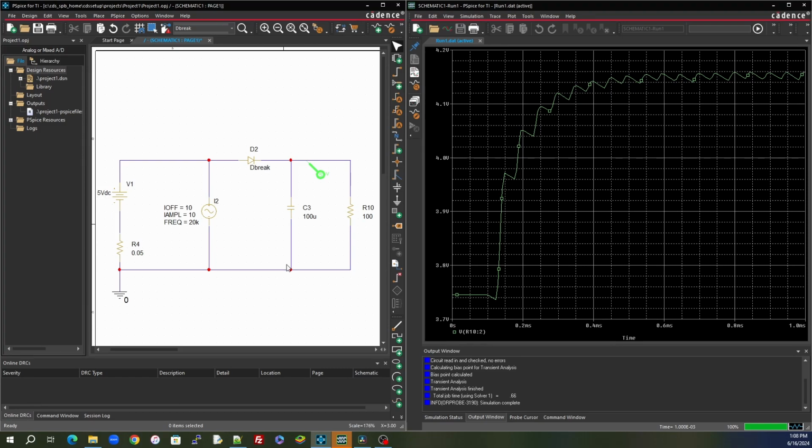So what we really want to say is, when the voltage of the battery is higher than 4.5 volts, go ahead and let the battery charge our system, right? But if that battery drops below a certain value, then put this diode back in. So we want to be able to take this diode and put it in and out.